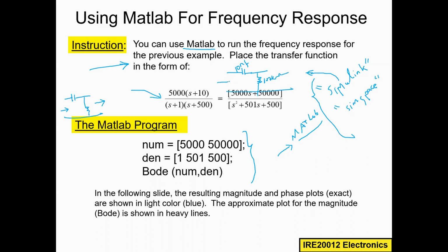And for the input, you can also take an input source, something like this, plus minus, and you can select what magnitude you want to apply. Maybe you want to apply 10 volt, and the frequency may be 50 hertz or 60 hertz, whatever. Then you can have the oscilloscope.